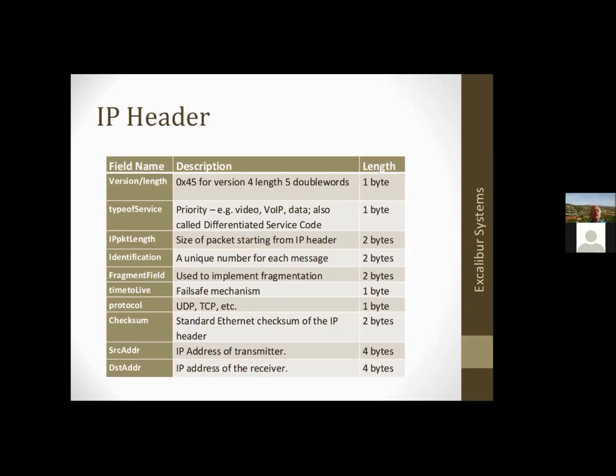The reason is that while TCP is a lot safer, it's a lot more unpredictable in terms of its timing. And it turns out that on an aircraft, even more important than the data getting there correctly is it getting there on time. And in order to predict the timing, we have to know in advance how many packets are going to be sent.